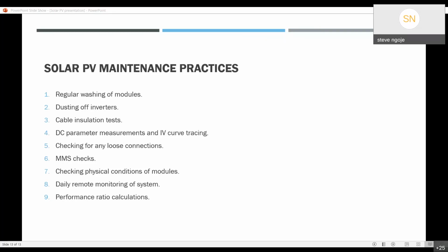The devices are meant to have CTs, the current transformers, and we also have the ability to tap voltages. Based on this, it will calculate your load connected at every given time based on how much current is drawn, and also calculate your energy usage at every given time.